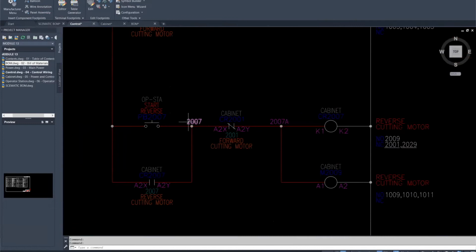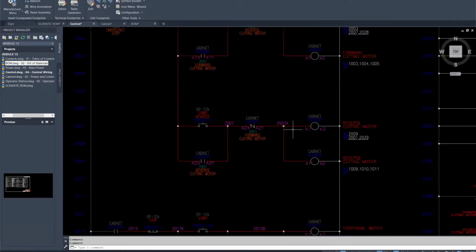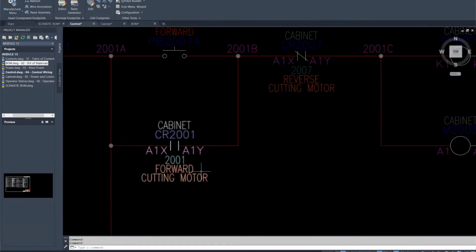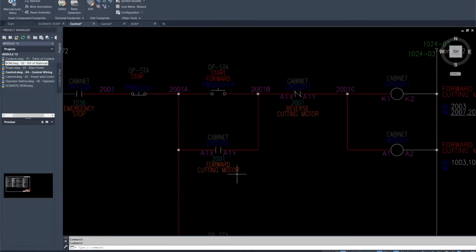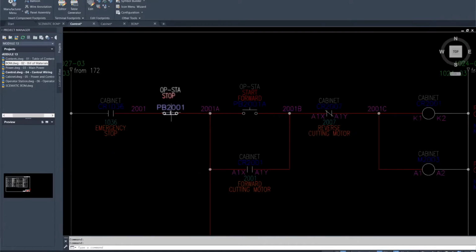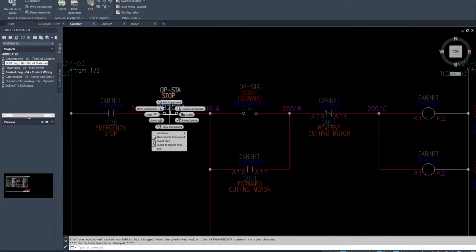what a schematic is built up of is components. And if you're used to normal AutoCAD, if you built schematics in the past with AutoCAD, you drew components and you turned them into a block. You inserted those, connected them with lines. AutoCAD Electrical has the beauty of connecting things by wires, and each component is a smart component where it has information that goes with it.